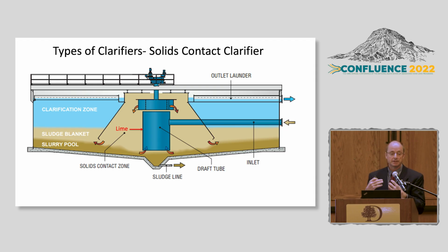It's really the same, but we actually are recirculating way more solids than you can with an external recirculation. So again, you're building these particles. We can add flocculant in this location. So growing particles, flocculating and producing a slurry that settles very quickly and produces a clear overflow. Okay, so that's a solids contact clarifier.